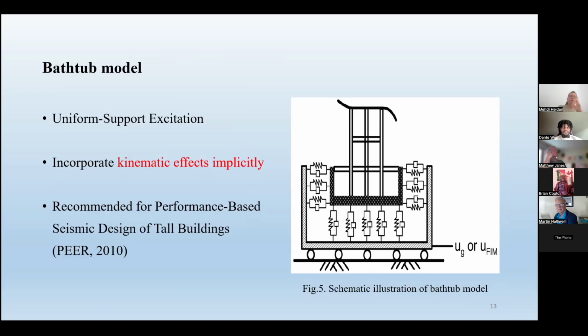And we have two different types of interactions actually when it comes to buildings. We have kinematic interaction, the free field: when we have an earthquake, we have the soil that is moving, and then it applies some load to the entire sub and superstructure. And the inertial force or interaction comes from the weight of the building, right?